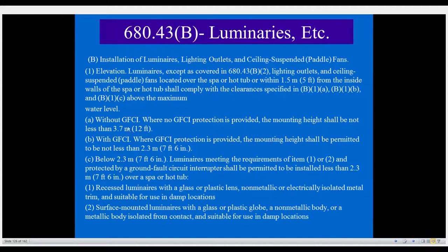So I can have a paddle fan that goes to 7'6", which is probably going to correspond with its listing, which could not be lower than that anyway. But when I want to go below that, I'm only dealing with luminaires. So again, the fan's going to stop about right here. Okay, so there you go. You've got some applications here.